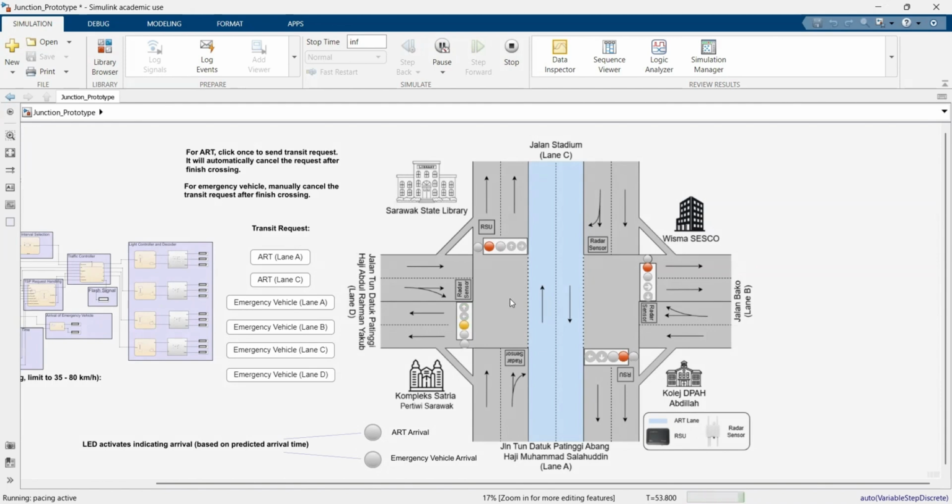After 30 seconds, it will turn to red and change to lane C, which is with high congestion level, served for 45 seconds. After 45 seconds, it changed to lane D, which is an empty lane, so it only lights for 3 seconds and turns to red. This scenario shows how the traffic congestion can be solved by the adaptive time control. And that's all for traffic congestion solving.